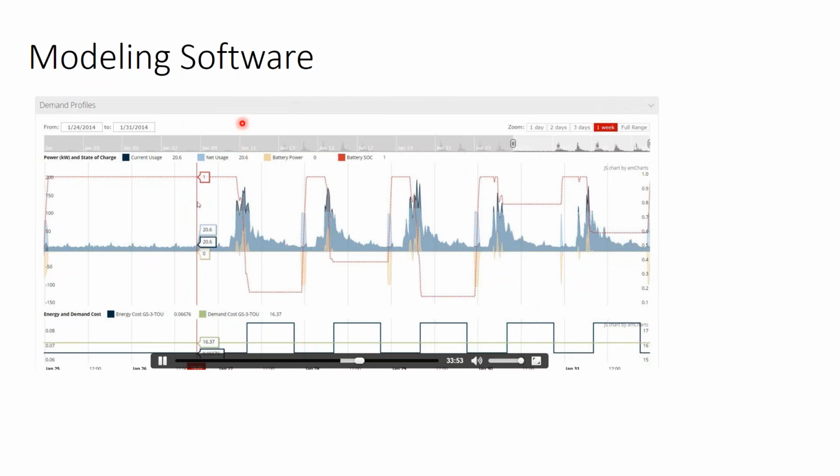And essentially, to model demand management, you have to look at a 30-day range of your building demand, and then kind of guess or set the level that you want to demand manage. And if you want to demand manage more rather than less, the further into this curve, if instead of load leveling at this point across the board, if we wanted to load level down here, we would have to be running our battery for a substantially longer period of time.